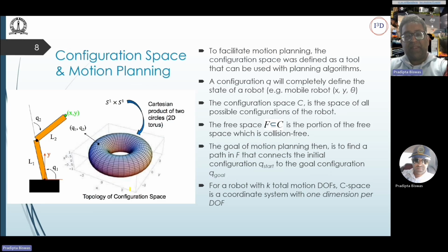So this is again an example that we discussed in the previous lecture. This is a very common robot that you can also buy as a DIY kit from Amazon or anywhere, where there are 2 motors and each gives 1 DOF. One is Q1 by the angle and the other Q2. And the configuration space is defined on the Euclidean space. Remember, I am not telling you this is the XYZ workspace. This is the Euclidean space defined by the sets of real numbers. And here the robot's configuration space will be defined by this torus. And how we are getting the torus, we'll see in a second.